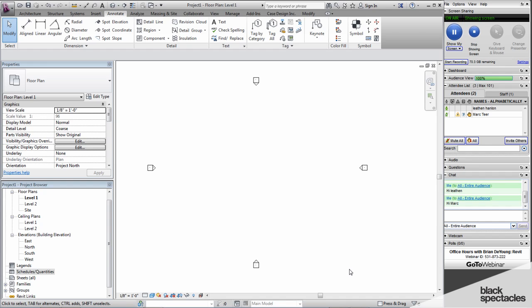All right. So I mean, it really depends on who's doing the modeling. You know, I would say for architects, it tends to be easier for them, particularly on high-rise projects, to model columns going from level 1 up to whatever level it is, you know, 20, 30, what have you. But for structural engineers, the structural department in my office, they always model the columns from level to level.